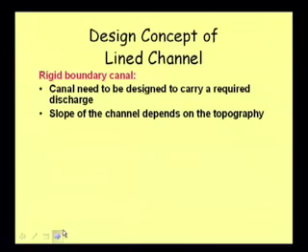But now, when we talk about the slope, you can concentrate on the slide, the slope of a channel depends on the topography. That means we have hardly much scope to play with that particular parameter. Say we need to design a canal in a particular location to carry discharge from one point to another, then the natural slope or natural topography will guide what the slope should be. There we can play by a very small amount.